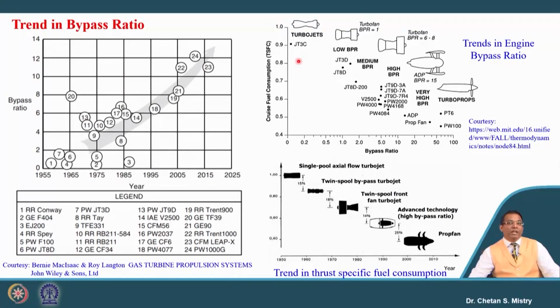People have realized their suitability in terms of fuel economy also. They have taken the turbojet engine as a reference engine, and with that they have shown over the years the variation of bypass ratio and the improvement in terms of fuel consumption. So, low bypass ratio engine, medium bypass ratio engine, high bypass ratio engine, and this all represents very high bypass ratio or ultra high bypass ratio engines.